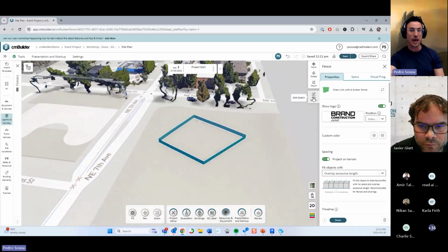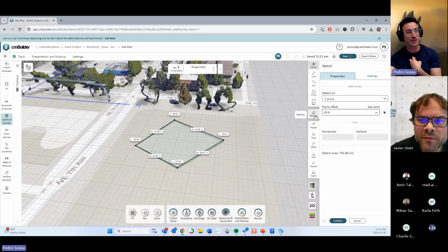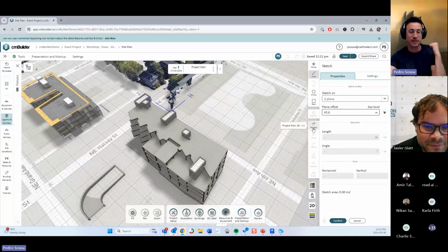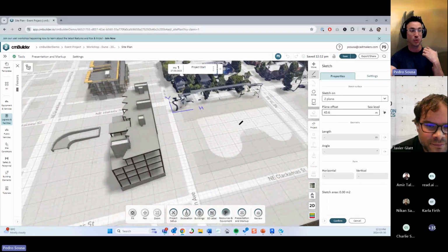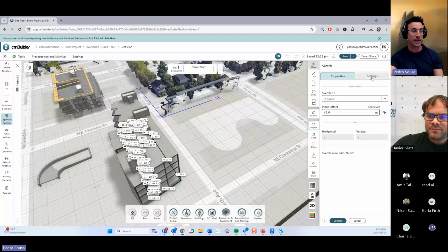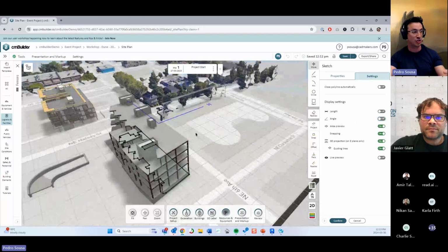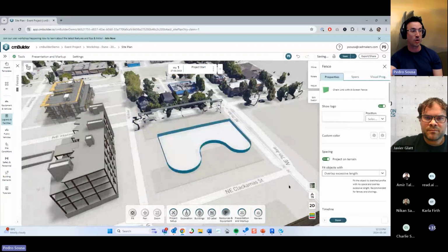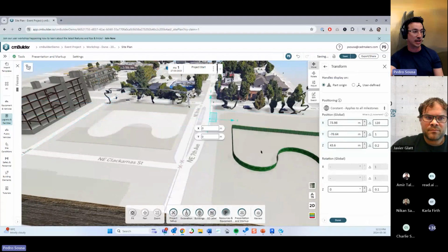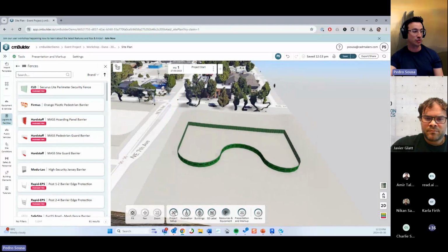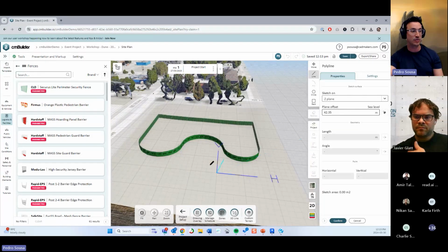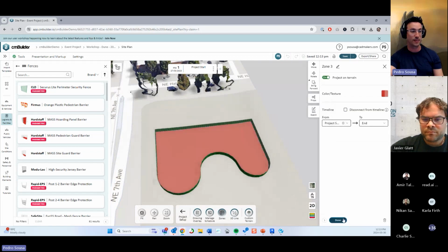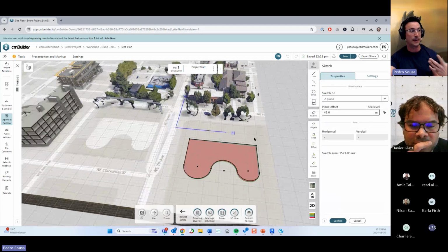Cool. So another thing is the projection tool. This is one of my favorite tools in cmBuilder in general, because it allows me to save so much time when I'm drawing things, right? I think I mentioned in the previous workshop that before, it would only apply to existing geometries like 3D models or massings, but now the projection tool also allows you to use zones as reference, or even other resources that are controlled by lines. So for example, if I put this fence over here and I want to draw a zone that is exactly the same shape as the fence, I can click my zone, start my sketch, click on project, select that fence, and it will fill up that fence with the zone that I want. Cool. So the projection tool is great. You should try to use it to save some time.